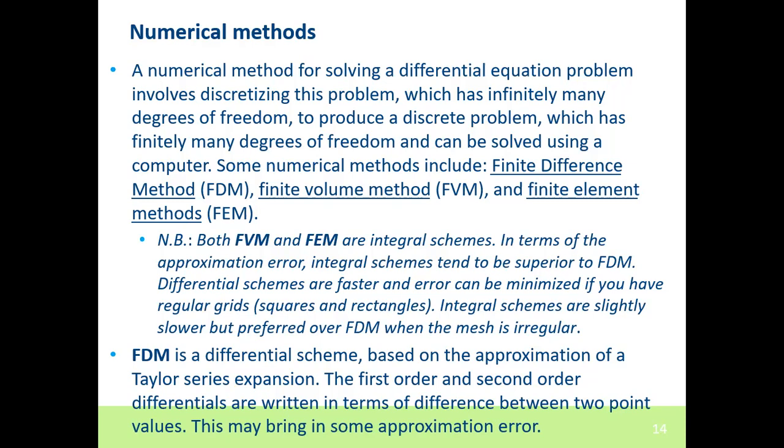So both the finite volume method and the finite element method are integral schemes. And in terms of approximation error, the integral schemes tend to be superior to the finite difference method. However, the differential schemes are generally faster, and the error can be minimized if you're using regular grid systems.